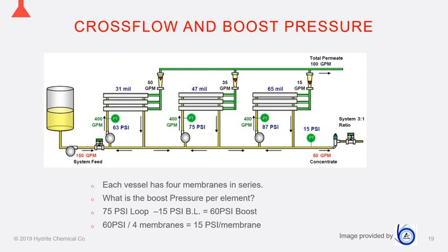And we always refer back to the membrane manufacturer's guidelines. We typically follow Koch Membranes, K-O-C-H. They do a really good job on specifying spacer size and element pressure differential, whereas some of the other membrane spec sheets just kind of give you a general guideline and don't give you an individual membrane number. So if you need any of that information, it is written in here, but if you want specifics, contact us or go visit the Koch website with your membrane information and you can look that up.